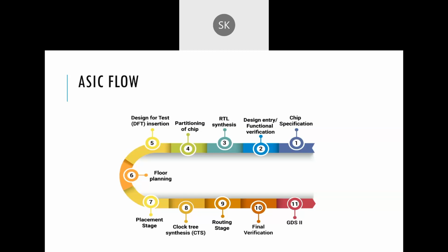We have some on-die debug systems, on-die debug components, so that they can measure the fault on the chip, and then they can resolve it, or shut it down, or do some fix like that. We have that circuitry on it. So in design for test, we are checking all those models and searching for all those faults on the chip. After this, we have the floor planning, like in which direction the components should be placed.